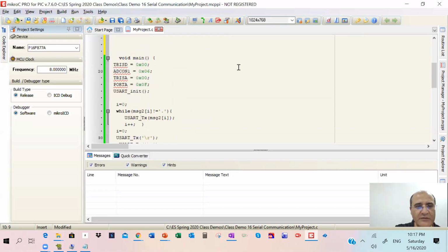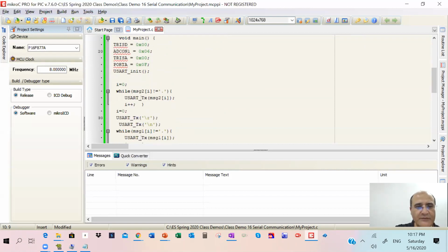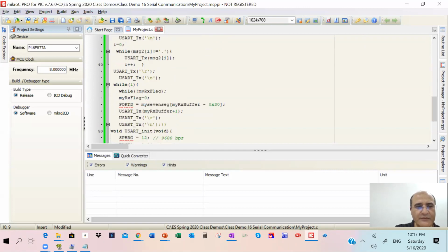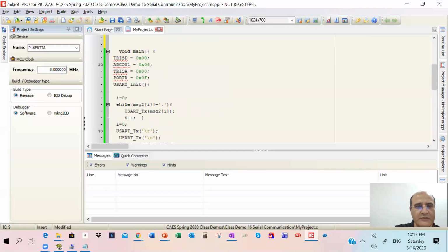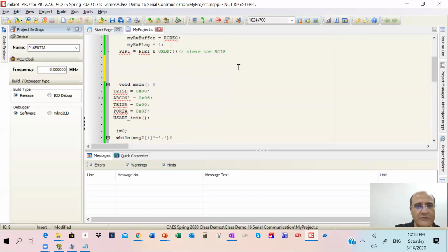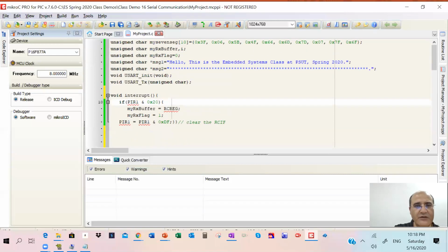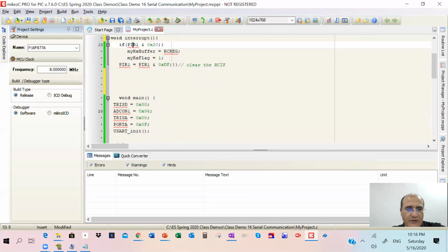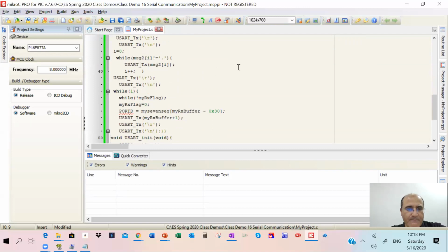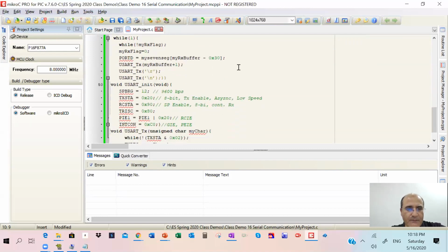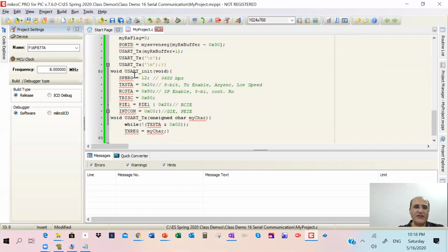Where did we enable the interrupt? Where did we enable the interrupt, Belal? INTCON, where's the INTCON register? INTCON. See? In the initialization, I did it in the initialization. When I initialized the USART, okay, let's do this. I initialized the USART. What did I do?